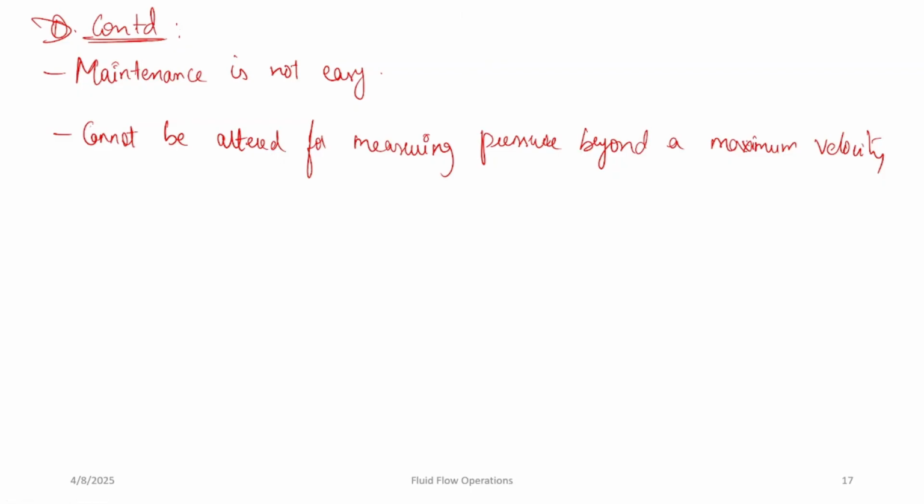Let's take an example and see how we will be able to use this venturi meter. Calculate the flow of water flowing through a 40 by 15 centimeter horizontal venturi meter where the differential gauge connected to the inlet end of the meter and its throat shows 25 centimeters Hg. Assume the coefficient of discharge as 0.98.